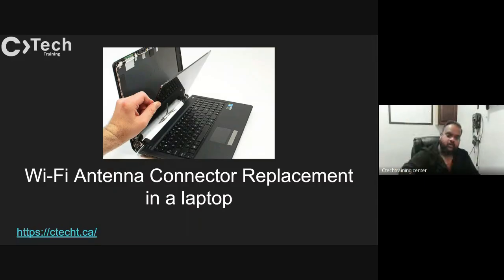But your Wi-Fi antenna, and this is why it's so tricky, and usually your antenna is okay, you never need to replace unless you actually end up stripping the cable when you try to dismantle the laptop itself. It's actually behind the screen. So you have to remove the bezel, remove the screen, and then go to the back. Nowadays, on a modern laptop, the screen is very, very thin, and it's glued to the back panel because it's not held by screws. So when you remove it, there's a higher chance of damaging the screen, which is $400 for the screen itself, just to replace the antenna.